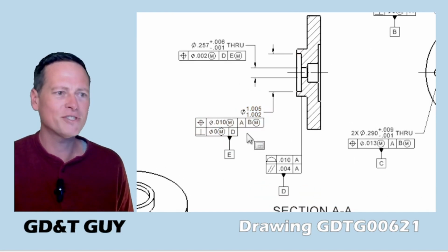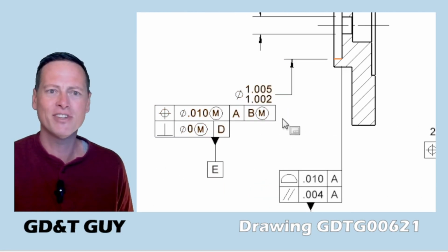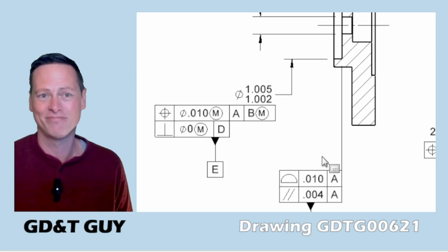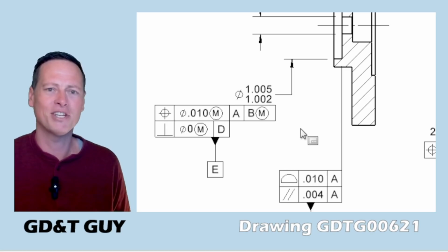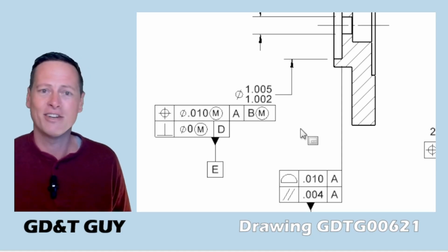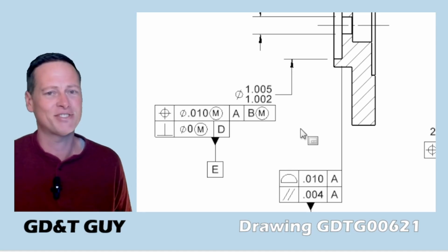Maybe we could force a datum C tertiary reference into this call out for the 1-inch diameter feature. I should think about it some, but I have my doubts about whether there is a scenario in which that could matter. I want to stick with my interpretation of 4.15, functional datum features, that tells us we should reference only the required datum features. And tertiary rotational constraint is just not required here.